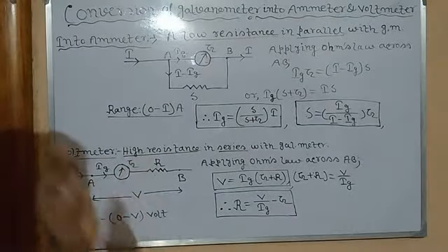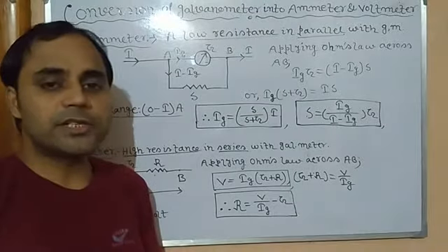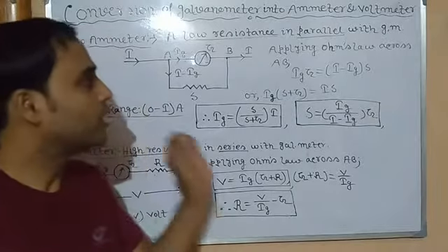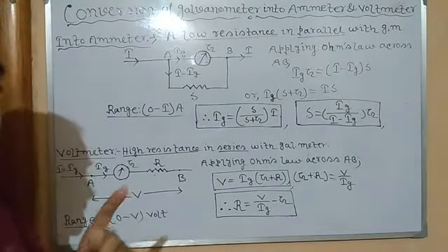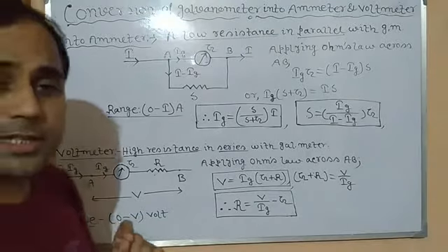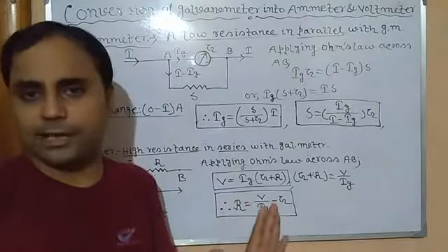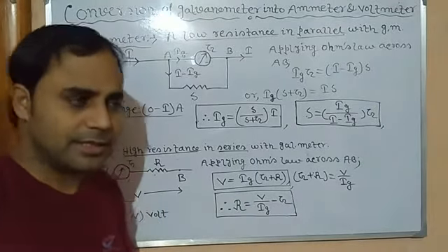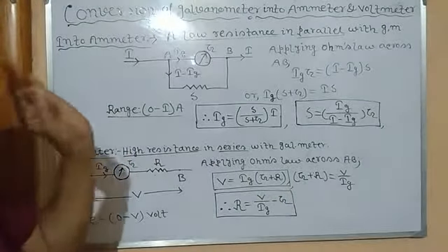So that's why we can say that the ammeter is an instrument which has very low resistance, and it is connected in series with the main circuit. Practically it is not possible to have zero resistance since it has some coil. Ideal means ideal condition, which is not possible in practice, because ideally it has zero resistance. Practically, it is very low resistance.